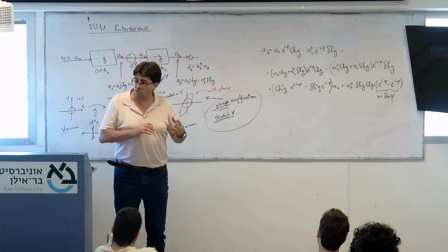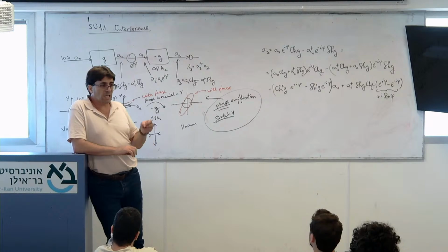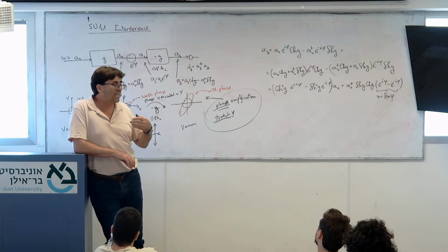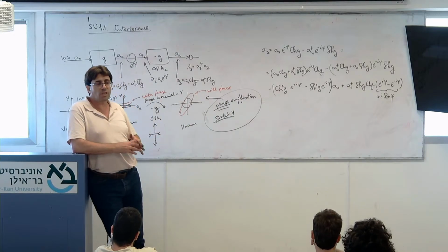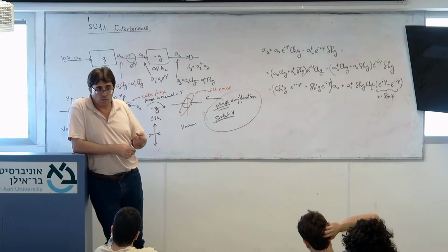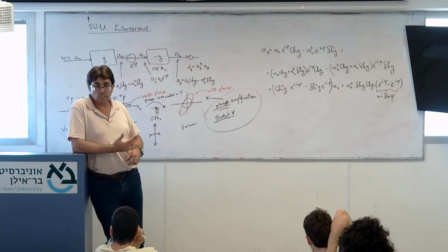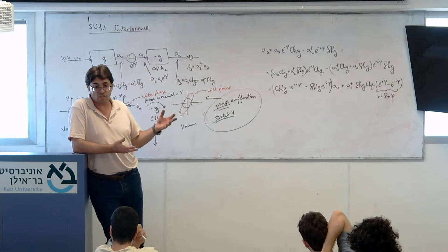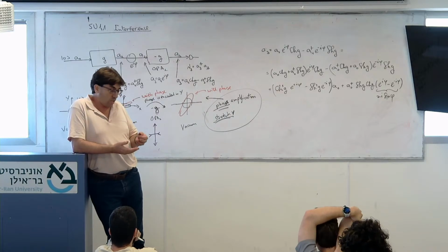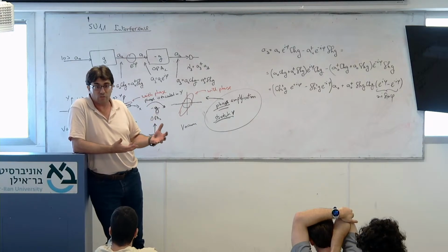So that's one reason why this is good. Generally, it is good to put an amplifier before you measure, because then you take out of the equation the detector noise. Detectors are always noisy. Detectors have dark count, meaning they generate signals even if nothing is there. They have amplifiers and all kinds of electronics inside which will generate noise.